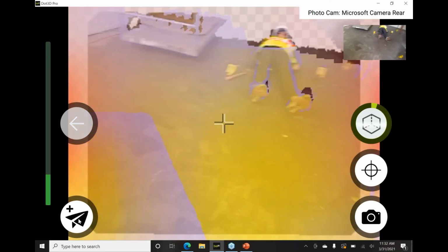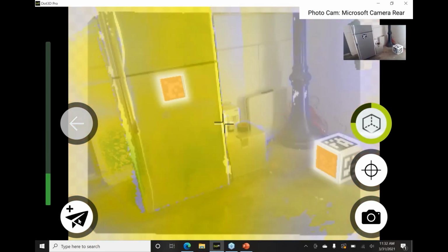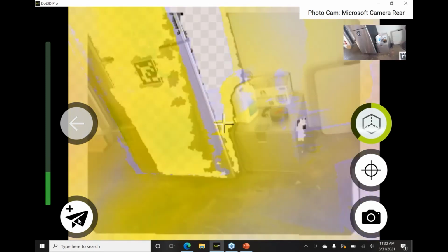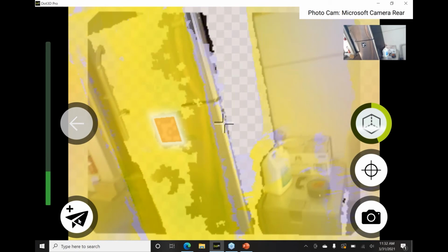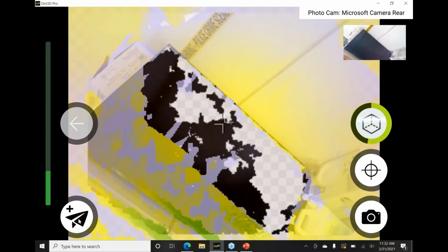So with that, I'm going to finish up our quick sample scan here. Always make sure to start and finish at the same area called closing the loop. And ideally, you want to close your loop on some April tags like we're doing now. Get some more data on this wall and then finish up.